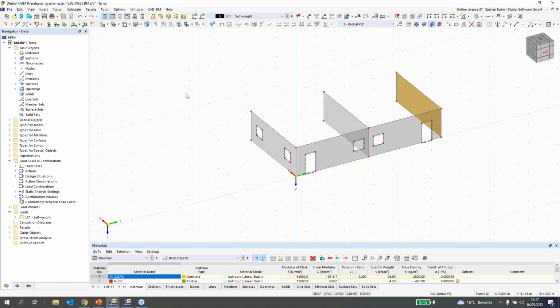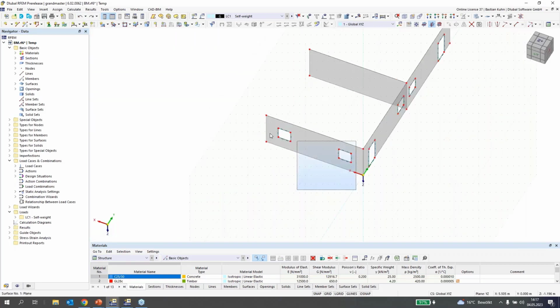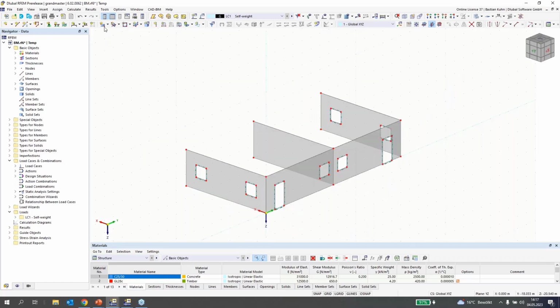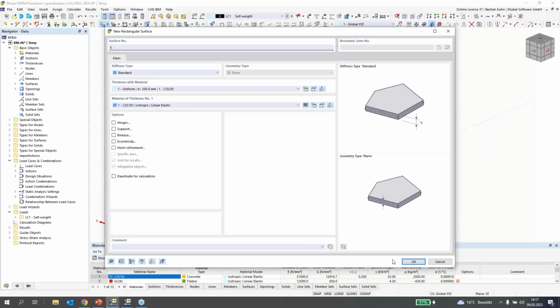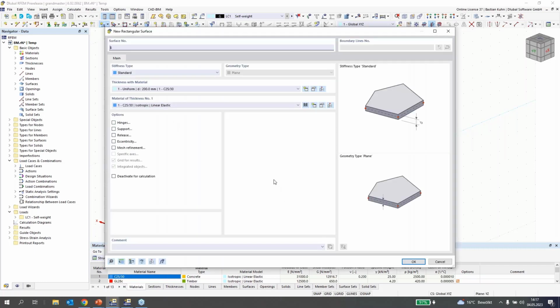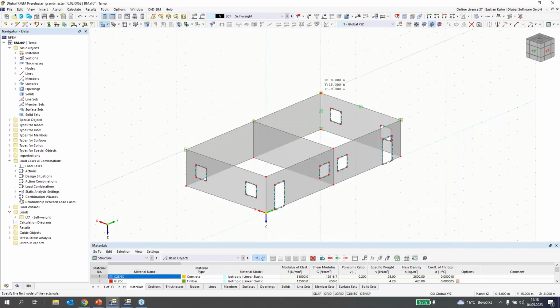All right. Oh, too bad. I should have activated also the openings, but now I can do that, and it saved all my inputs that I had. Okay, so this is the ground story. Well, it's open on one side. That I should change. 11 centimeter and top. And maybe we make a thicker surface on the top with 20 centimeters. We can just keep that.